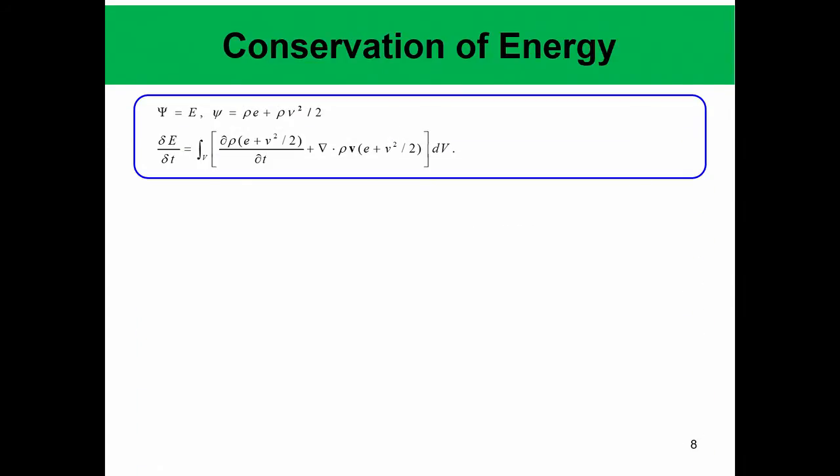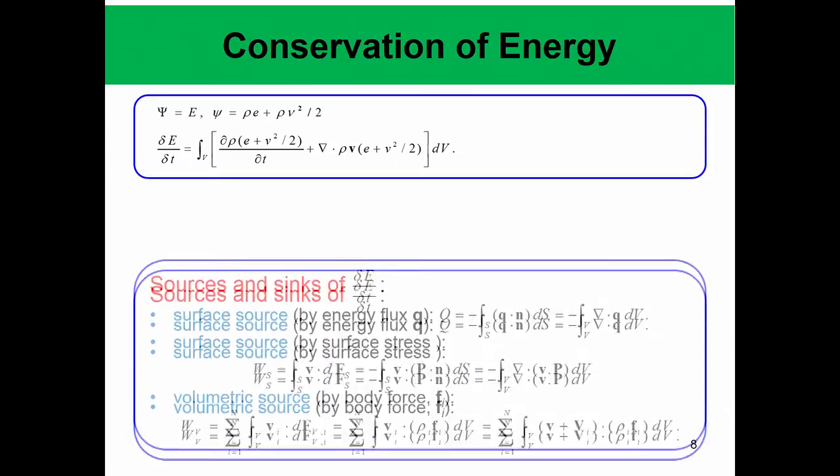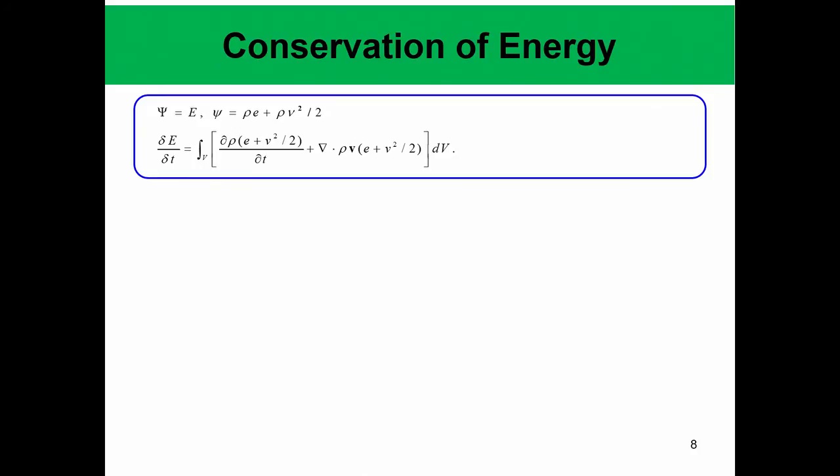Finally, the conservation of energy. This is actually the most complex equation, and it is also the most important when it comes to combustion, because in combustion temperature is the king, and we will see later that from this energy equation we will derive a useful form for temperature. So this transport of thermal energy will come from this conservation equation.